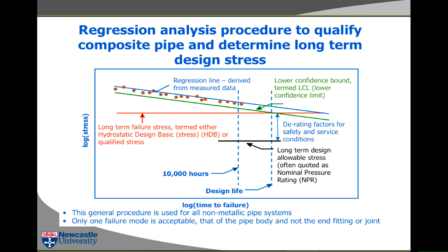And there are a number of standards that refer to this. The standards will tell you how many points you need to have. So you put a pipe under constant pressure, you wait for it to fail, and you measure the time to failure.